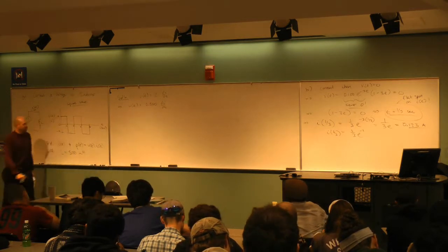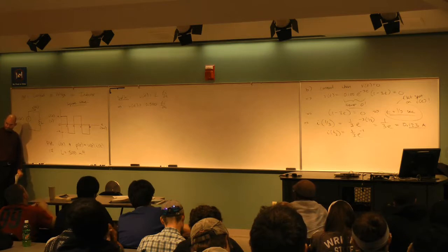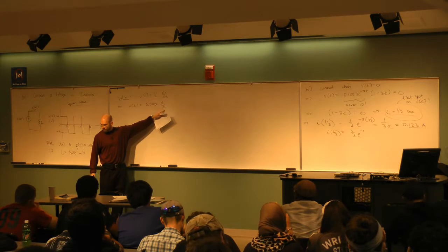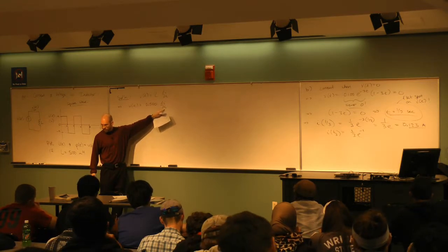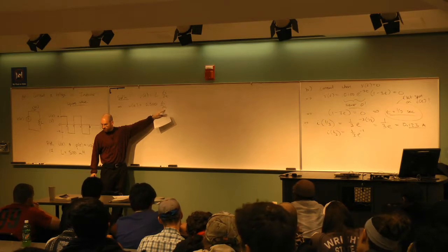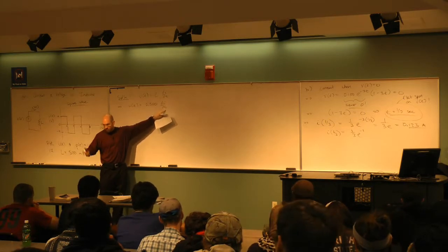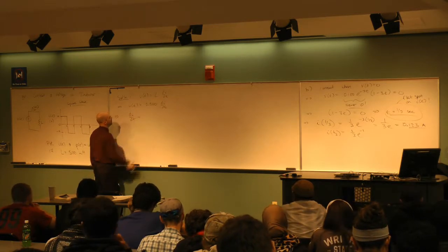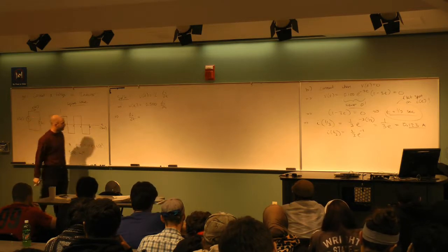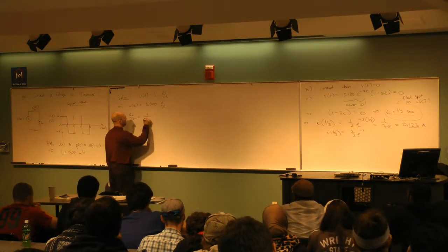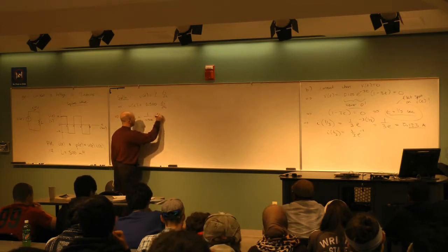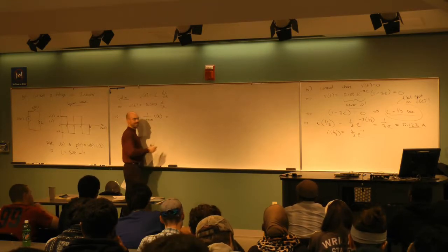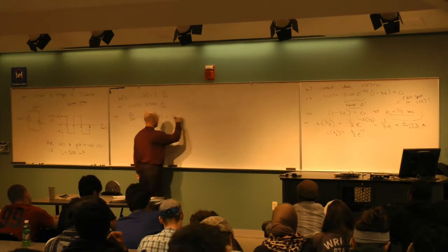Now, the first thing I want to plot here is the I. This is a statement about how the voltage relates to what? The derivative of I, which graphically speaking is what? It's the slope of I. So maybe rewrite it so you can say, what's the slope of I then? di dt. If I solve for di dt, what do I get? It'd be 1 over 0.500 times the voltage, right? 1 over 0.5 is the same as what? 2, right? 2 times the voltage.